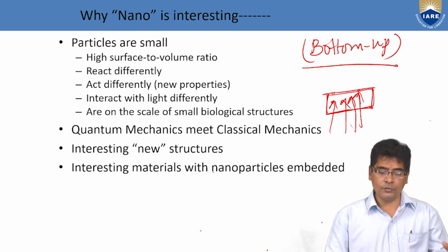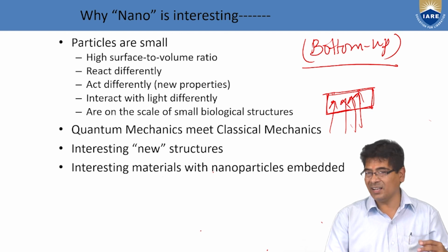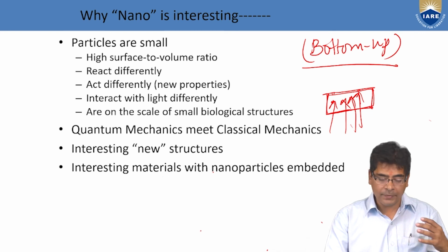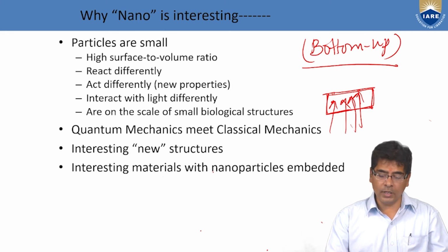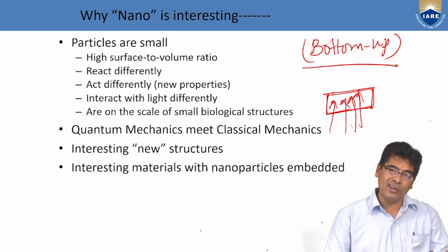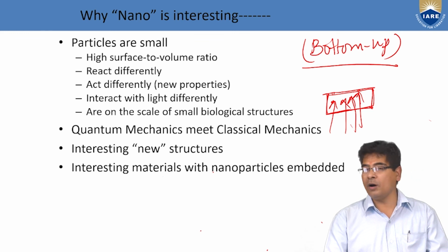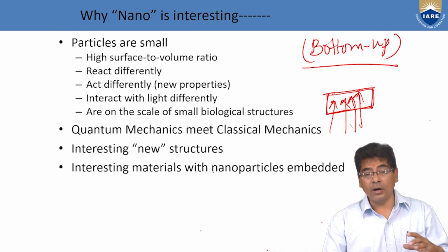The solution is deposited on the substrate by spraying, dipping, or spinning. The particles in the sol gel are polymerized through removal of the stabilizing components to produce a gel. The final treatments pyrolyze the remaining organic or inorganic components and form either a crystalline or an amorphous form of the nanoparticle coating on the substrate.